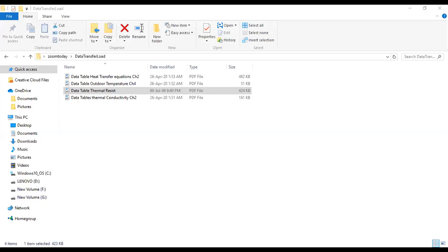You have to calculate heat transfer through glass separately. You know, heat transfer through the glass has two parts. One, solar radiation, other, transfer due to temperature difference. Solar radiation is direct heat transfer inside the building by radiation, and that is given on a per square meter basis. That is a separate table. But there is a temperature difference between the outside surface of the glass and the inside surface of the glass.